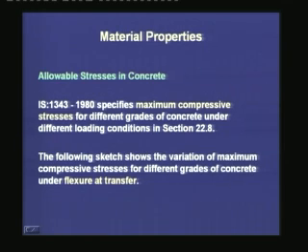Next, we are moving on to the allowable stresses in concrete. In prestressed concrete design, as we mentioned earlier, there are three important stages of loading. The first one is at transfer, when the prestress is being transferred to the concrete, the member should be able to sustain those high stresses. The second stage is the intermediate stage, when a prestressed concrete member is transported from the casting site to its final location, then it is subjected to stresses. And third, in the final location, the prestressed concrete member is subjected to the loads during its service life.